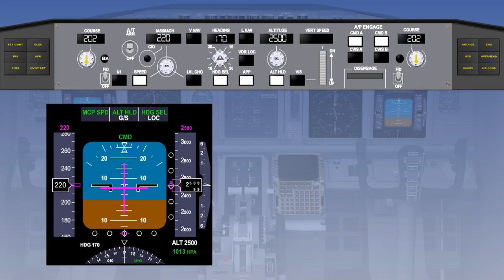The second and/or third autopilots are now referred to as offline channels, as they are performing all of the same calculations as the first autopilot based on their inputs, and are sharing information with one another, cross-checking, to make sure they are in agreement. At this point, however, they are not yet controlling their servo motors, which is signified by the command annunciation remaining on the primary flight display.